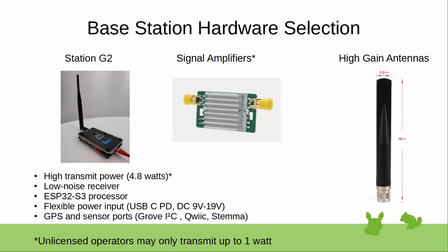But the Station G2s have the ability to get up to 4.8 to overcome some coax losses and other things as well. I forgot to mention that these guys are very low power, so these are more like a 1/4 of a watt. So it really matters for your elevation. Yeah. Even with LMR 400, if you have say 10 feet of feed line, you lose basically all of your power out of that. Mhm. So for the little guys, you more or less have to have it mounted straight to the antenna. Yeah, so the Station G2s are a really good workaround for that.